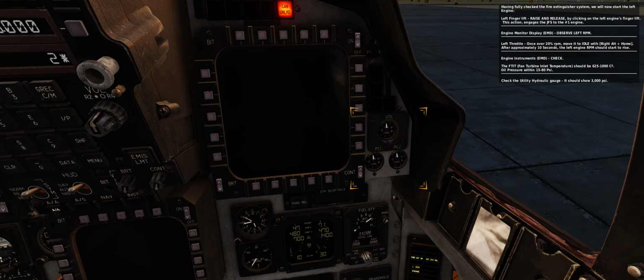Jet fuel starter. Confirm its green light is off, JFS switch still on. During the engine start, the JFS is automatically shut down after both engines are started. Canopy. Close if desired, with a right click on its lever. Locking the canopy causes a hydraulic block, so be sure to have the canopy completely against the windscreen, before placing the handle in the locked position with a second right click.